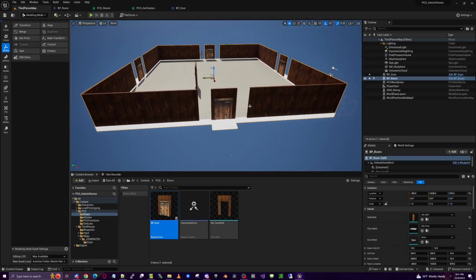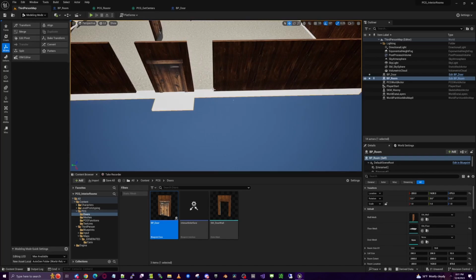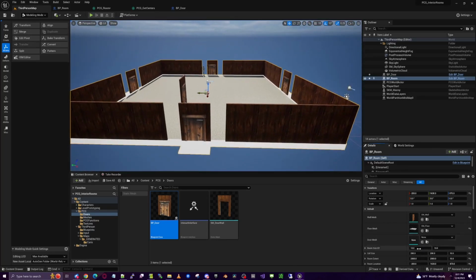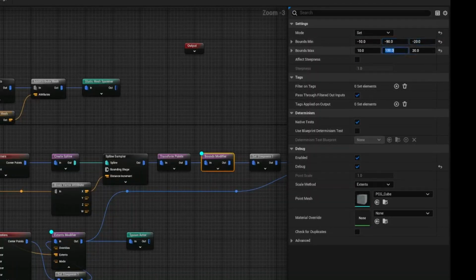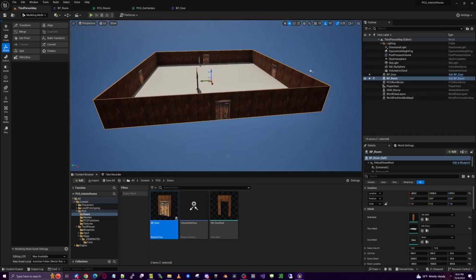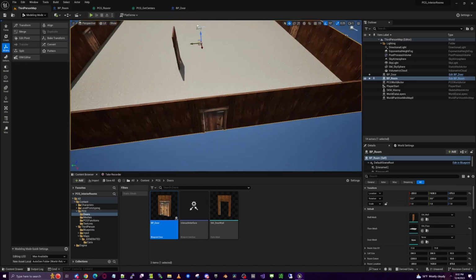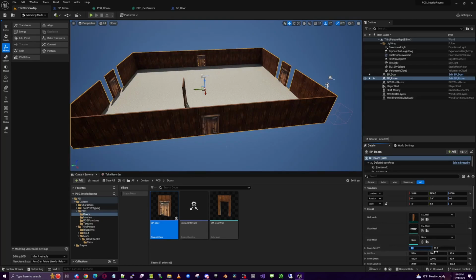We're still losing 2 wall sections, and we can see why that is. So this extent goes from here over to here, and the next extent goes from here to here. So we're overlapping with 2 wall sections. And the reason is because our room size is even. If we make this odd, now our door is in the center. And then if we shrink this bounds a little bit, so they don't touch, it's now solid. Because our true center was in the middle of 2 walls, and now our true center is 1 wall, so it works correct. But we want the rooms to be odd in size. So anytime they're even, we're gonna get that gap. So we want to make sure we always set those odd, and then those will be correct.